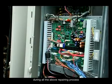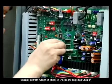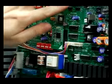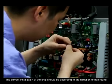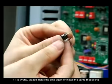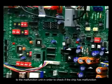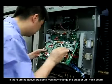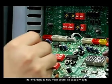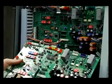During all the above repairing process, if the outdoor PC board needs to be replaced, please confirm whether the chips of the board have malfunction, such as pins of the chip falling off or chips plugged in the reverse direction. The correct installation of the chip should be according to the direction of the half round. If it is wrong, please install the chip again or install the same model chip to the malfunction unit in order to check if the chip has malfunction. If there are no above problems, you may change the outdoor unit main board. After changing to a new main board, its capacity code and address code must be the same as before.